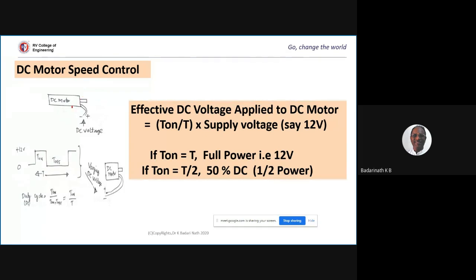So how does a DC motor work? All DC motors have just 2 wires, unlike the 5 or 6 wires you have in the stepper motor. Because in a stepper motor, you require 5 or 6 wires because you have to push the digital sequence into it. In the case of a DC motor, no digital sequence is required. You require just a voltage. That is why they provided just 2 terminals, like any other DC device.